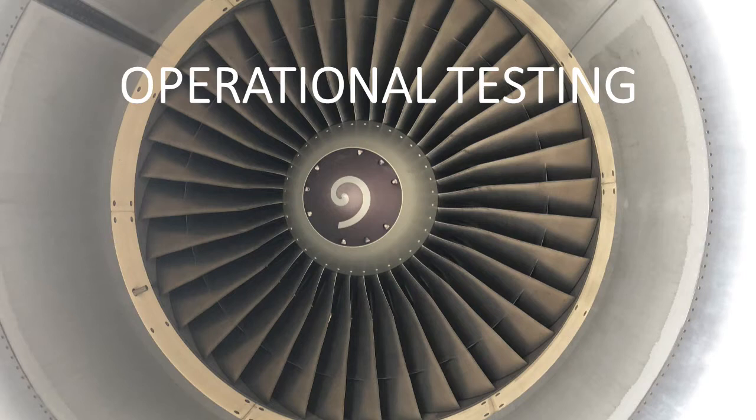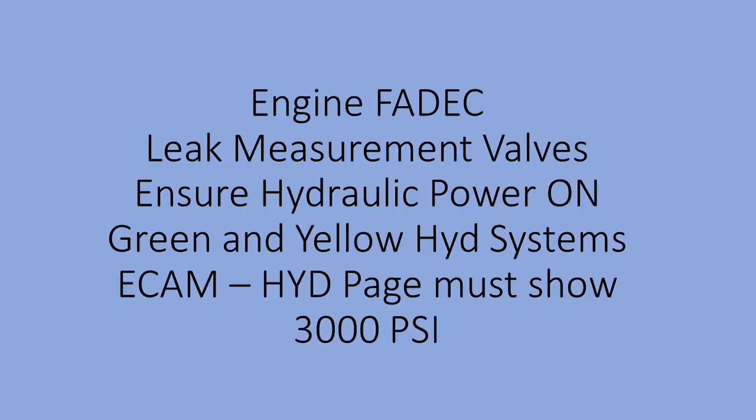And of course, when you do an operational test of the thrust reverse system that is actuated, because there are actuators also as components of the system, you want to make sure you have hydraulic power going to those actuators to move the blocker doors. So do make sure that you have the pressurization of the green and the yellow hydraulic systems.